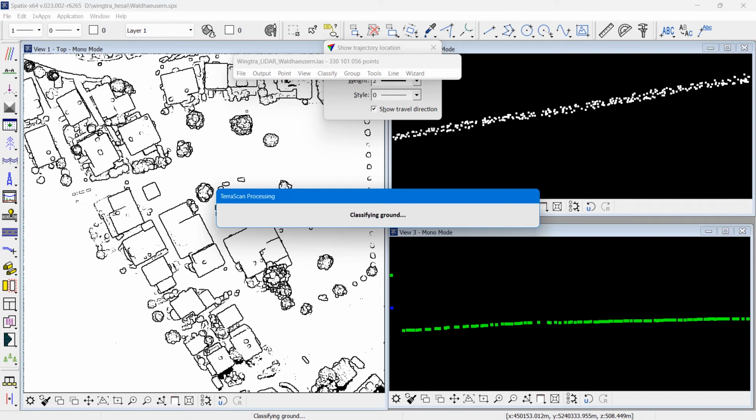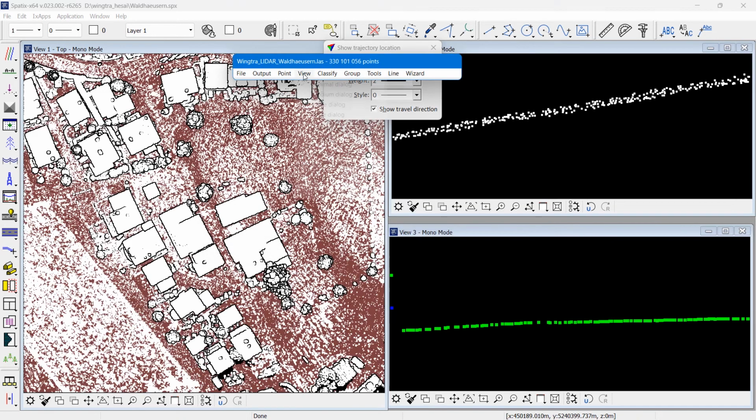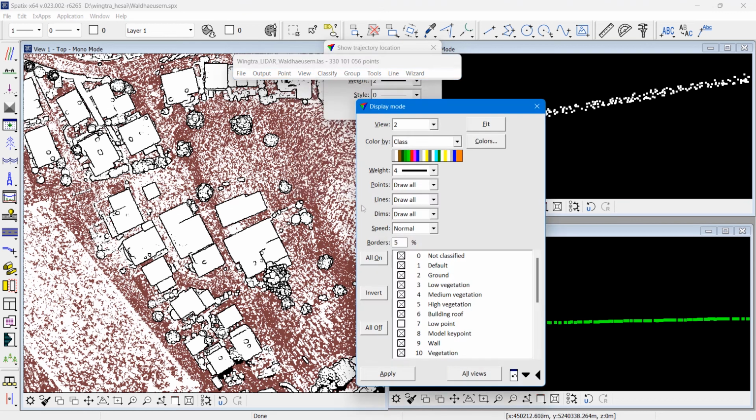But for most datasets, it is okay to do checking of the ground at the very end, to run all the wizard steps first and then do the operator work, checking the ground visually, at the end of the process. In this demo I will do the check ground right after classifying ground. So the ground classification has classified some of the points into class 2.